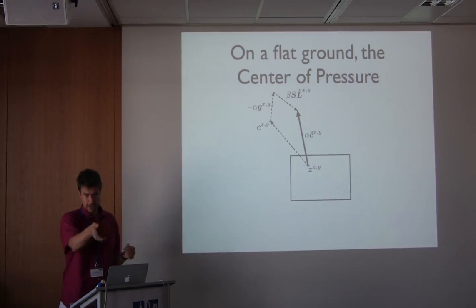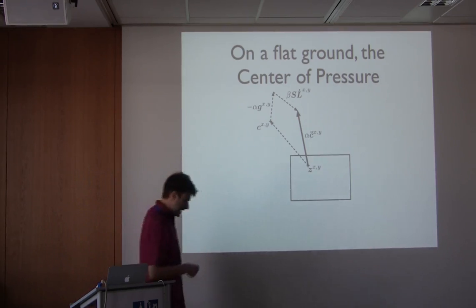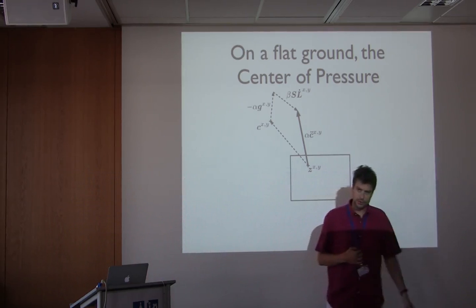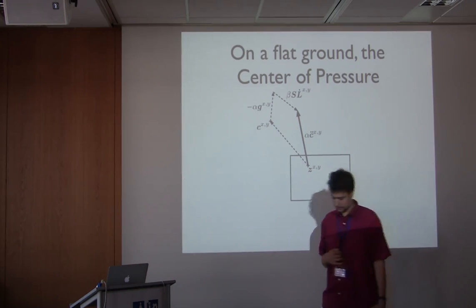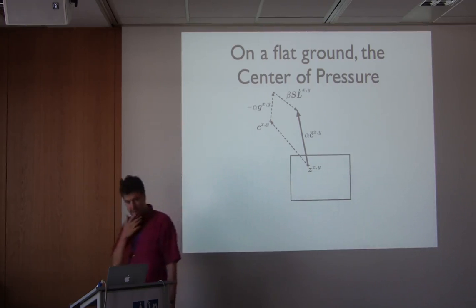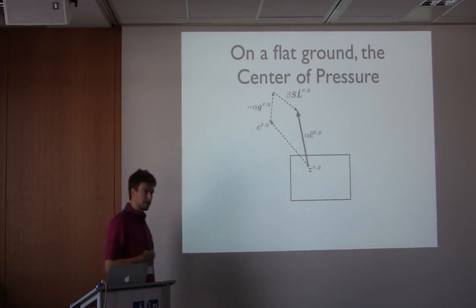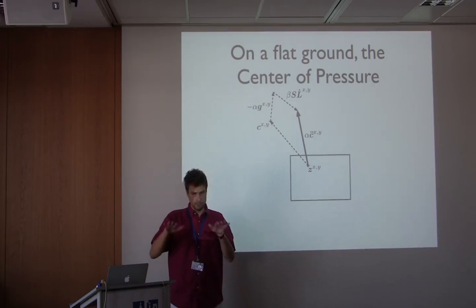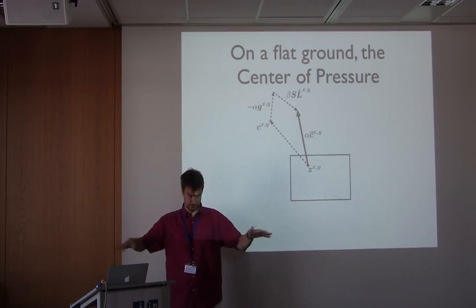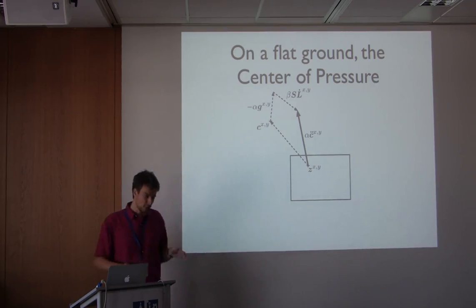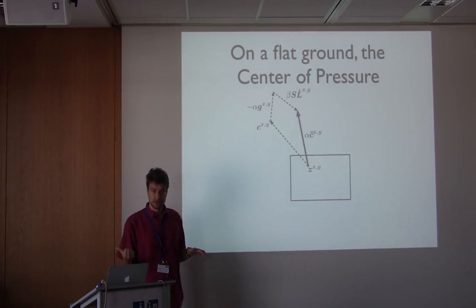So in the paper I discussed a little bit about friction. It happens that it's not such a problem usually for walking, so it hasn't been the main focus. You can have some problem with friction when you have both feet on the ground, because if you don't synchronize the two motions, then obviously you have some slipping motion. It can be a problem if you want to accelerate very fast, because of course the acceleration of the center of mass is related to the force. But normally robots don't accelerate that much, and it's not such a problem.